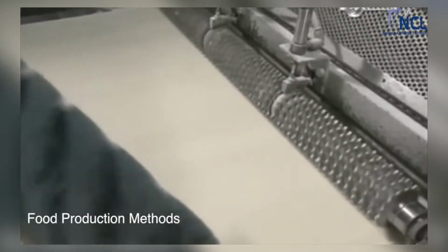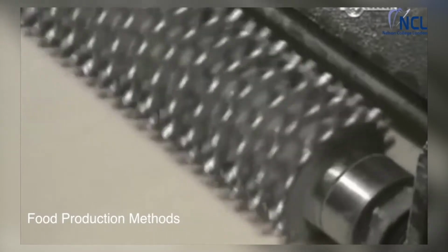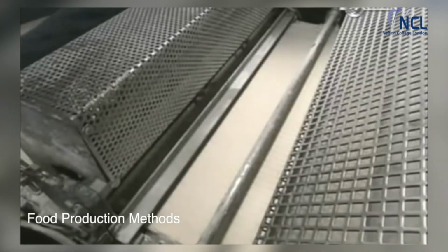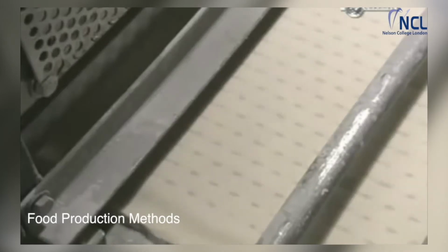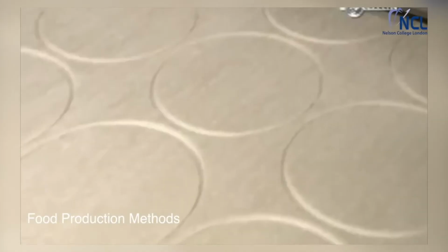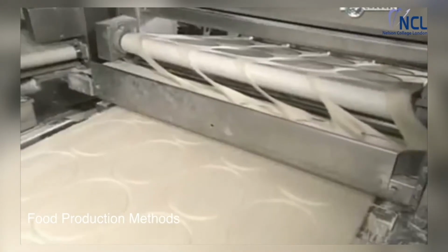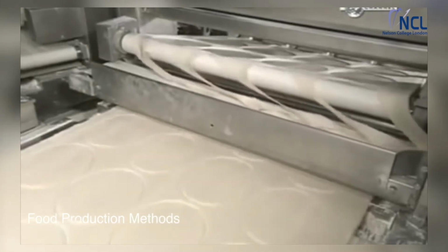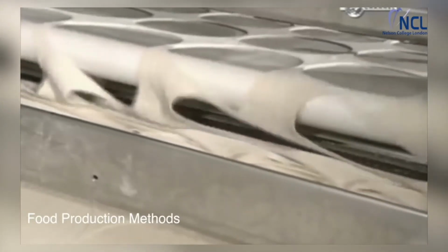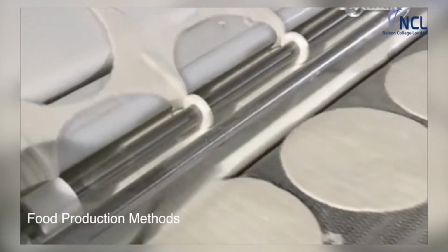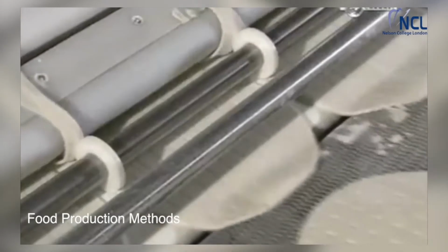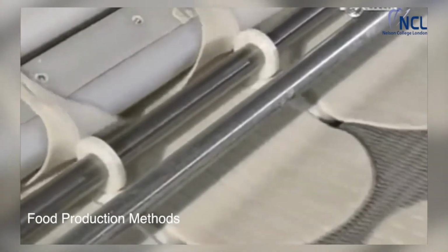Next, stainless steel spikes pierce through the dough with holes 7 to 10 millimeters deep. These holes will stop air pockets from forming in the dough. A large plastic roller with several round forms cuts the circular shape of the pizza crust. The machine automatically separates the leftover dough. The factory remixes it with fresh dough for the next batch. A conveyor takes the dough circles to their next destination, the oven.